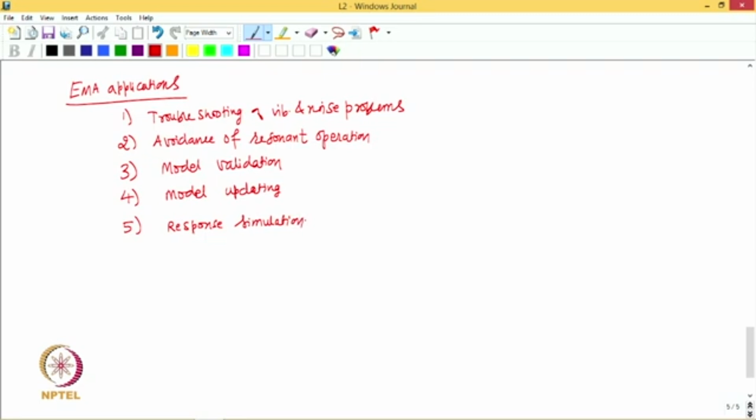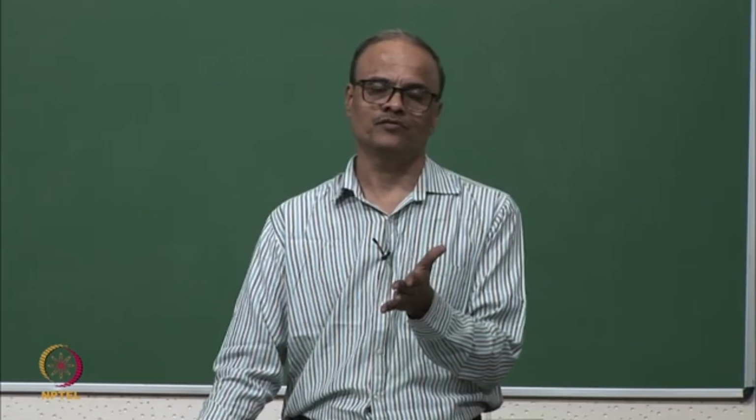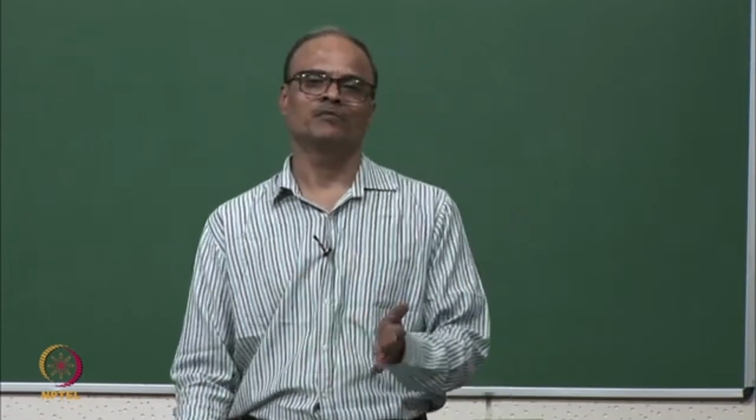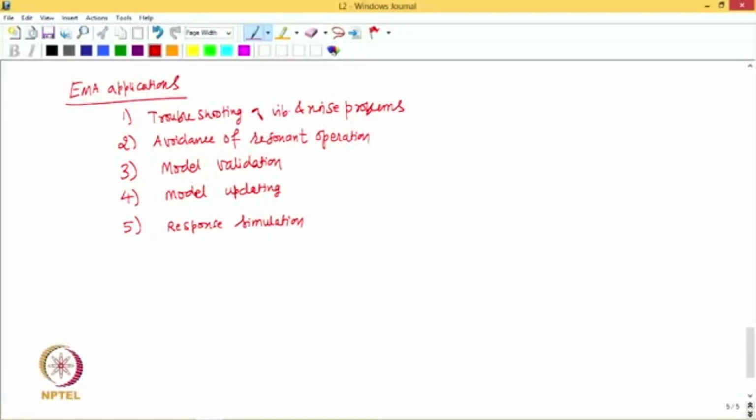The modal characteristics, or the model we obtain from experimental analysis, can be used to simulate the response of the structure to the dynamic forces which are likely to act on the system in practice. It can also be used for identification of unknown forces acting on the structure.